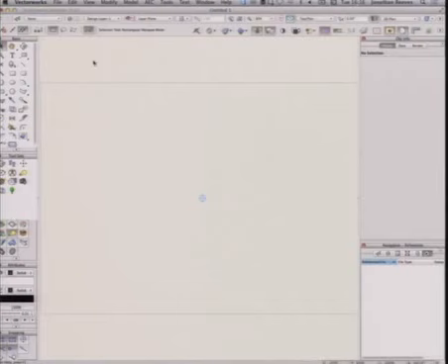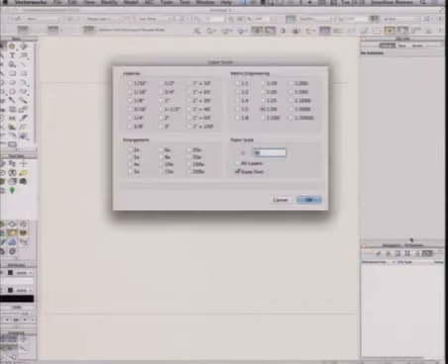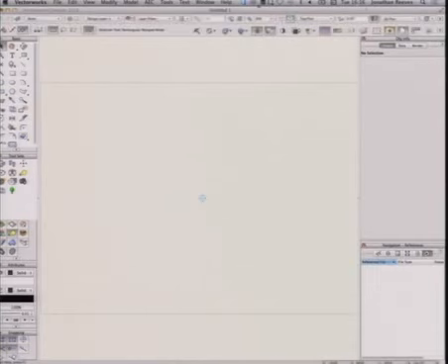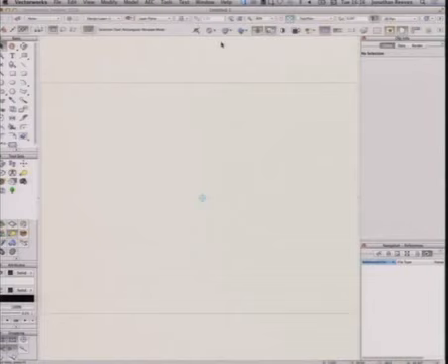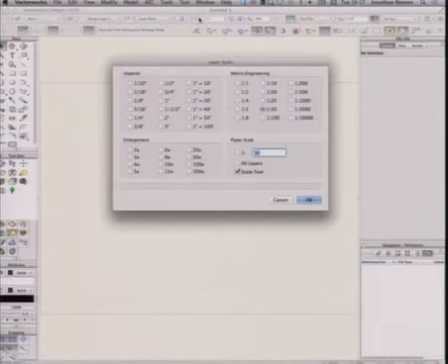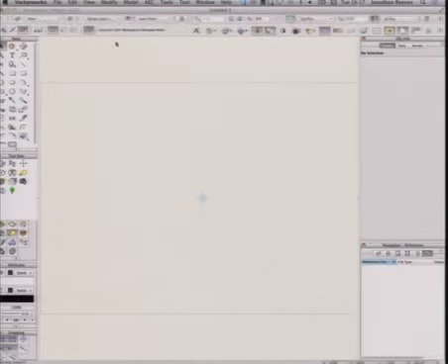Okay, so first thing I'm going to do, I've got my scale, 1 to 50. That's a decent scale to design at. In Vectorworks, choose the scale of design that is appropriate to the level of project you're currently engaged in. So on that New York project, clearly it was a 1 to 500 type scale. For house design, it's more 1 to 50 scale. We always work at 1 to 1, but we view at different scales. Don't model at 1 to 1 though. You should be viewing at the scale that fits.